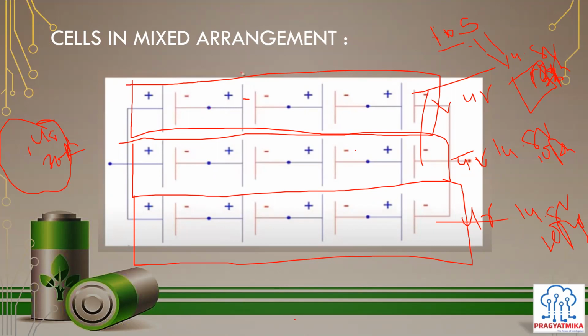Exactly. That's the restriction from the BMS point of view. The shortcoming of this is that you can't monitor the individual cells. If you want to develop a machine or a method to find out which one cell in the pack is going low or which one's capacity is fading, you will not be able to observe it. You have to break your battery pack, and only then can you test each and every cell and find which one cell has gone bad out of those 100 cells.